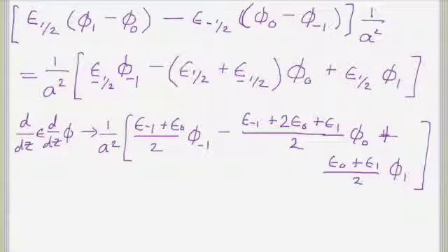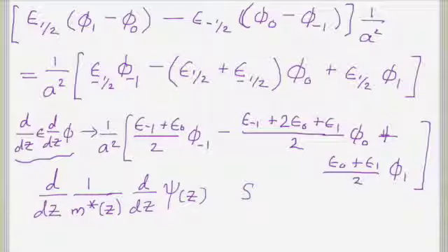Also note that, I don't know if we talked about this in 208, but the form of this is exactly the same form as you use when you discretize Schrodinger's equation with a position-dependent effective mass. So this is what you would do with Schrodinger's equation when you have a position-dependent effective mass. And you can see it looks just like our Poisson equation, where our epsilon becomes 1 over m.